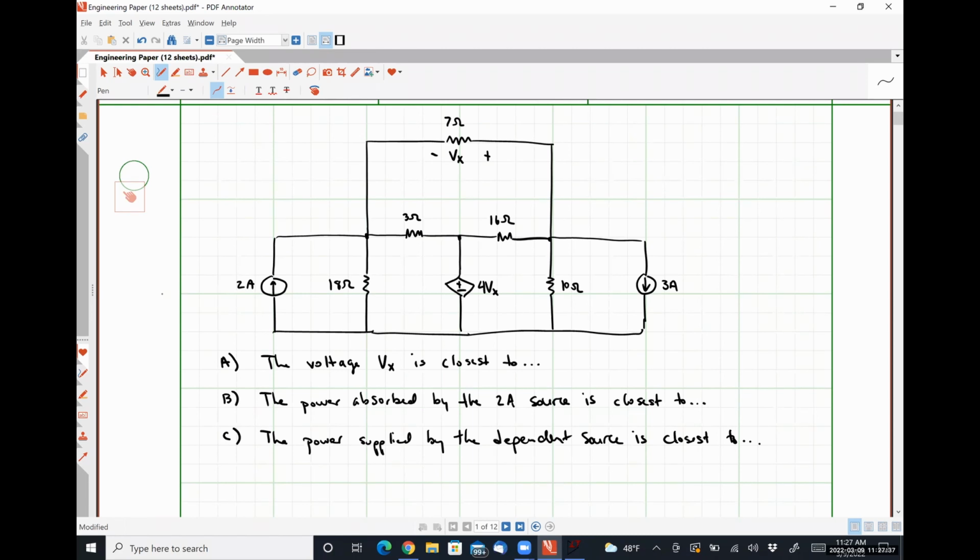So it's a 3 equation, 3 unknown system. Whereas if we did mesh analysis, there are obviously 5 meshes. We could simplify the circuit by doing source transformations on each of these wings outside, eliminating some meshes. But nodal analysis gets us the answer with the least amount of effort. So that's the way that I'm going to approach it.